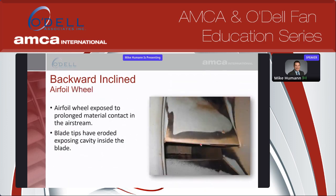Here's kind of the downfall of an airfoil blade. You can see here at the blade nose, we have erosion where it's actually eroded the blade tip, the blade nose away, and you're going to have further erosion. You're going to build up material in there, and then you start having balance problems. It's eventually going to lead to failure. So the trade-off there is the airstream with an airfoil needs to be as clean as possible to make the proper selection for that. Otherwise, you can have issues.